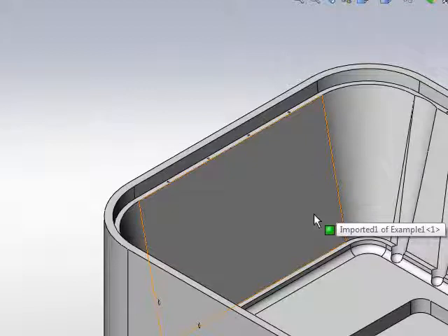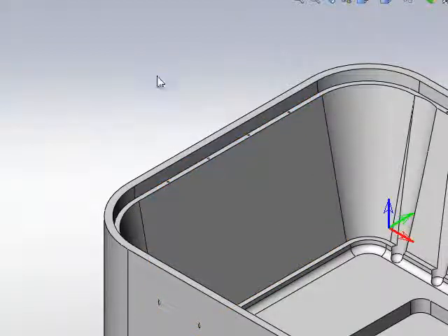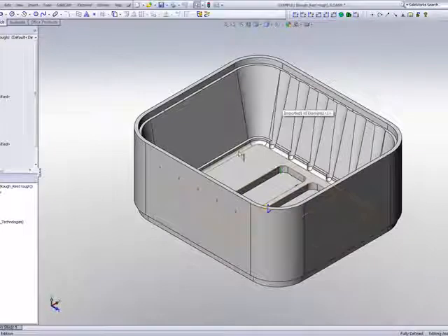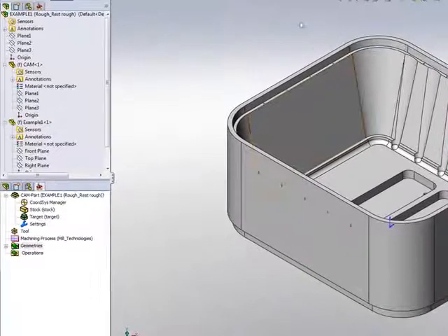our constant Z options. Now, what I'd like to do is go into this deep pocket while using a tool that's only sticking out a short distance from the holder itself. And we all know the problem with that: a lot of times the holder cannot go in because it'll crash into the walls.